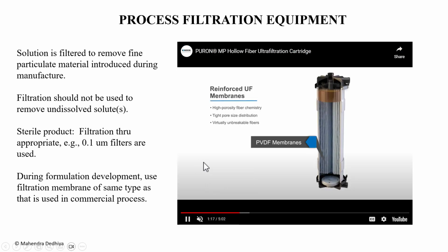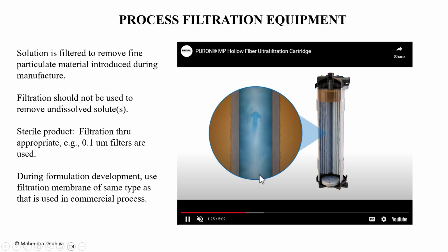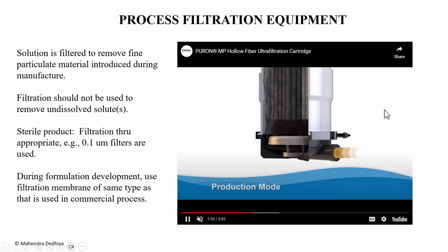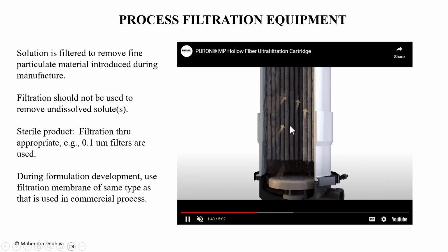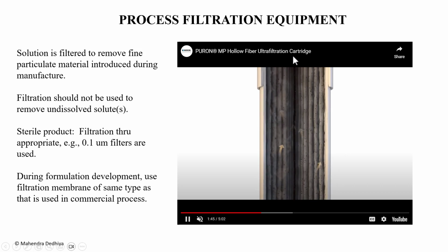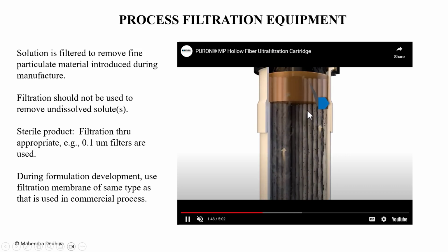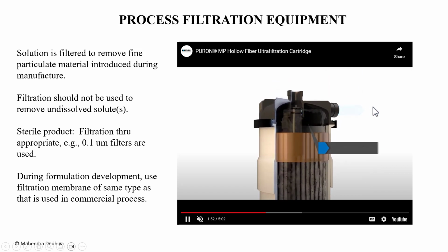So generally there is a membrane with a pleated surface, and liquid goes up from the bottom and is discharged from the top. So liquid is introduced here, with the particulate as shown, and the particulates are retained inside and clean permeate comes out.